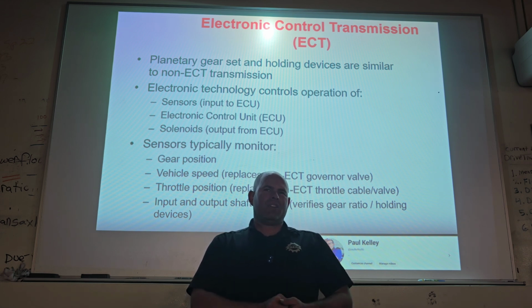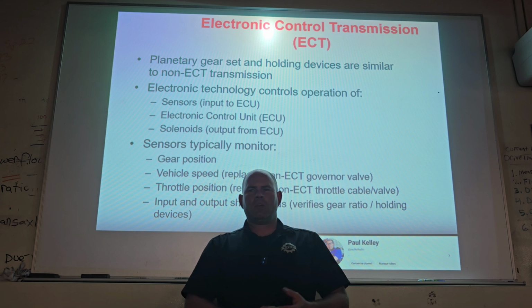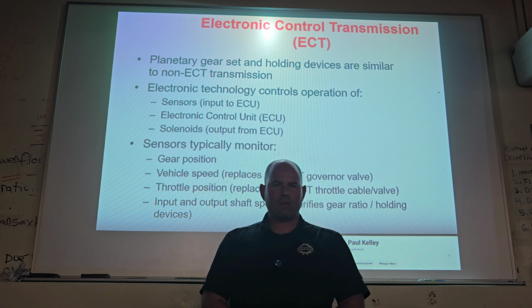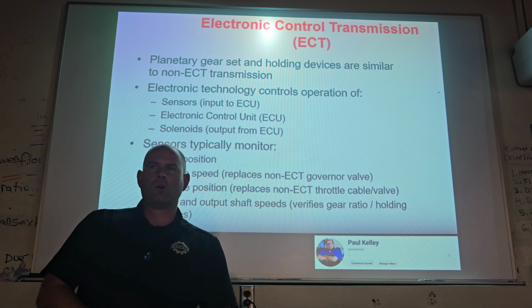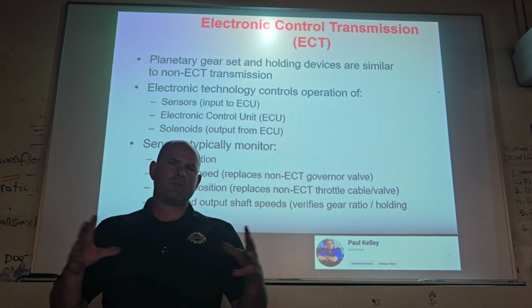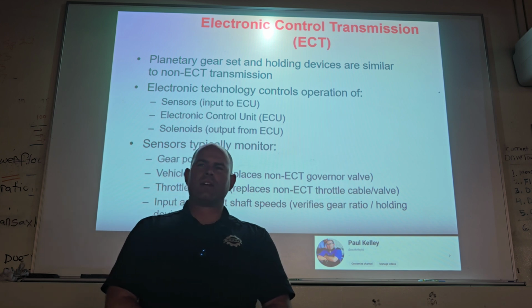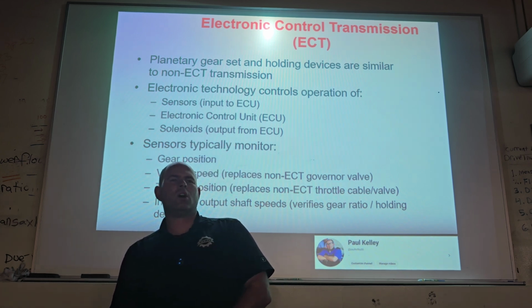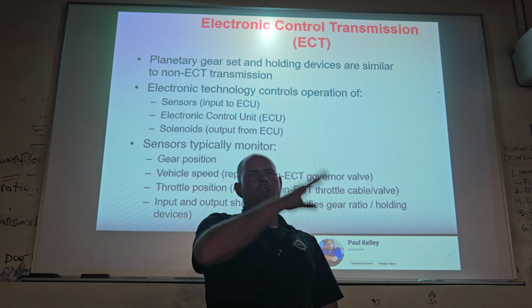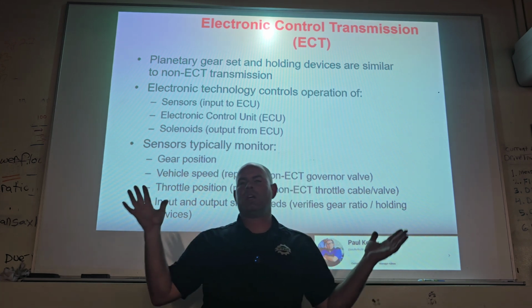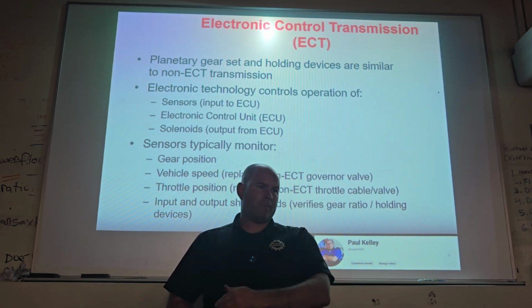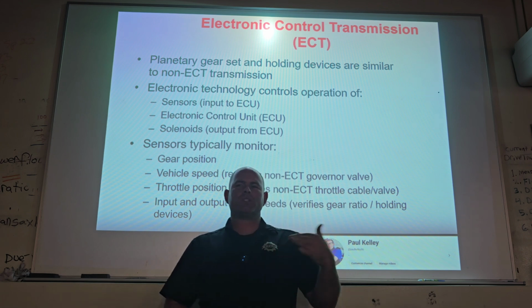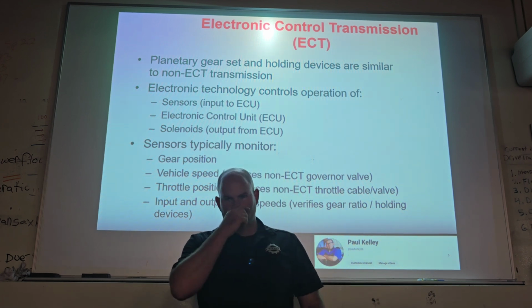Back in the day, if it was a hydraulically controlled transmission and there was a problem, you could always fix it by replacing something or adjusting something. Now, if the vehicle comes in and it's actually normal, and the real issue is that they wrote a shift timing that the customer doesn't like, we can't fix that. You understand? If the customer says, oh, when I'm wide open throttle, it runs all the way up to too high RPMs, it should shift sooner, we can't change that. That's not in our purview. An engineer would have to go in and rewrite the program. Now, if an engineer rewrote the program and published it as a TSB, you could fix the car. Do you know how you'd fix it?